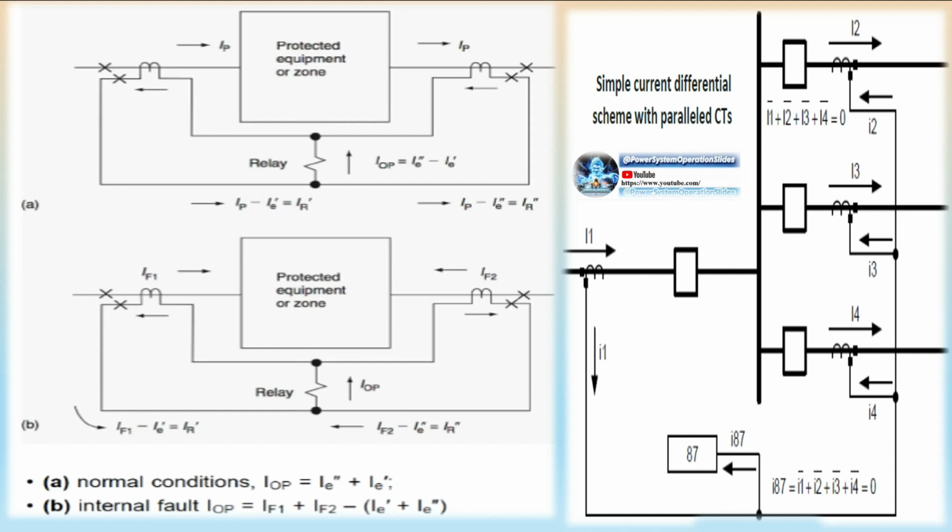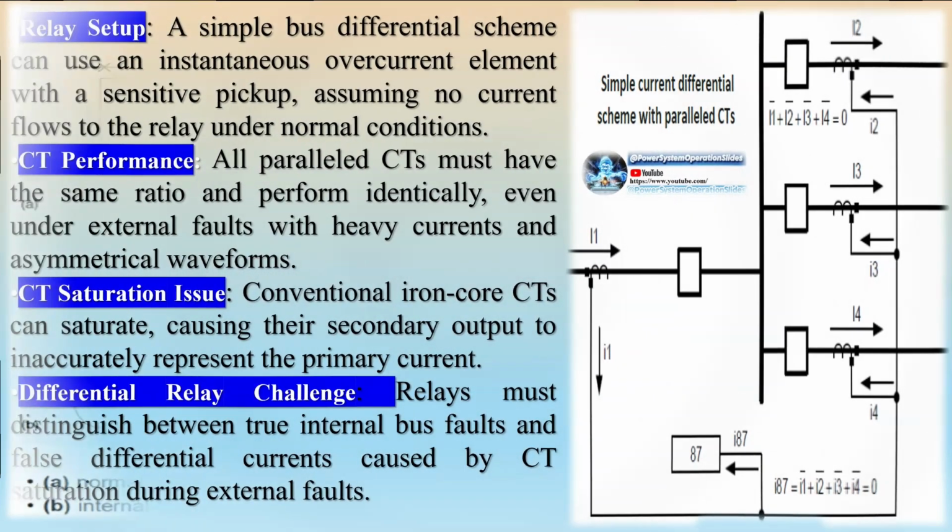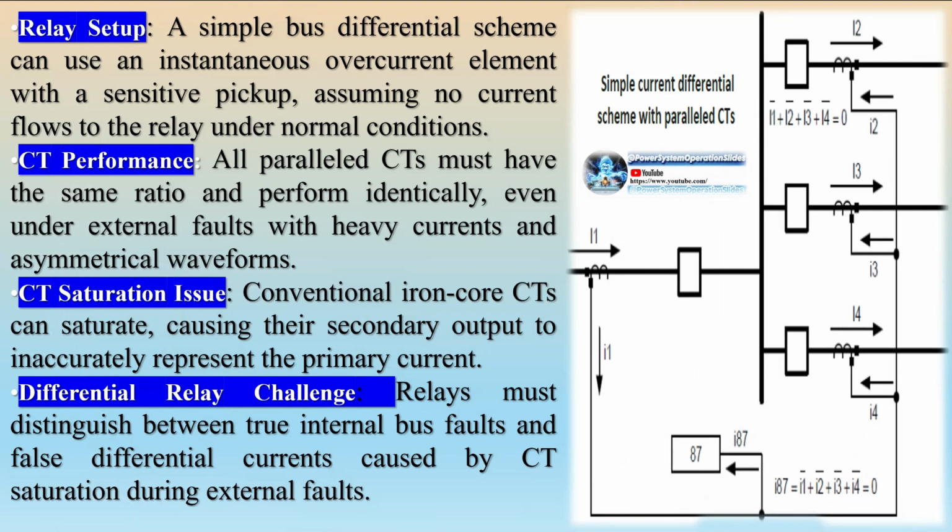Protection during on-load busbar changeover. The busbar protection system must be capable of detecting faults occurring during an on-load busbar changeover, ensuring that the connected bays receive appropriate trip commands. Bus coupler time delay. A time delay is necessary for bus coupler operations, which should be shorter than the delay of Zone 2 distance protection, typically ranging from 0.15 to 0.3 seconds. Policy for isolator alarm. The switchgear positional information is crucial for determining the primary arrangement of each busbar section, and policies may vary on how to respond to isolator alarms. These strategies and components are essential to ensure that busbar protection systems can effectively manage various scenarios and maintain the stability and safety of the transmission system.